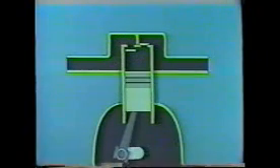During the downstroke of the piston, the pressure in the discharge line holds the discharge valve closed. Now the cylinder space is filled with refrigerant vapor. As the piston moves up again, it compresses the vapor into a smaller space at the top of the cylinder. Now the pressure in the cylinder holds the suction valve closed and causes the discharge valve to open.